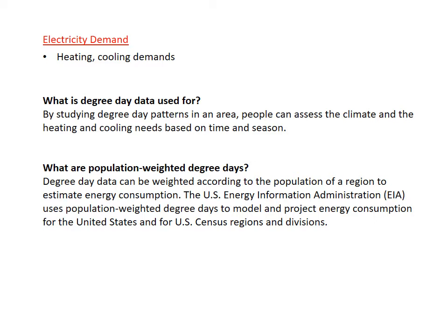Now, the one important consideration when doing that is that you weight the degree days for given areas by population, right? So if you were looking at two different states, and one had a much higher population than the other, then the increase in electricity demand per degree day is going to be much higher in the state where there's a lot of people that would be potentially using an air conditioner or a space heater than the state in which no one lives, right?